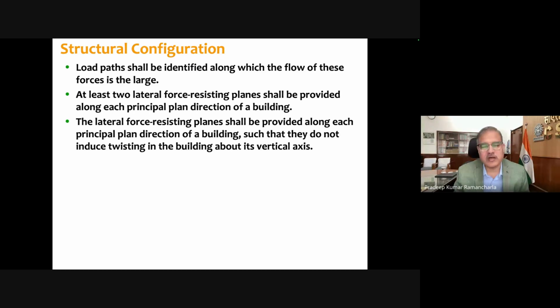Mainly what the code specifies is that in each principal plan direction, at least 2 lateral force resisting planes should be available. That is very, very important.